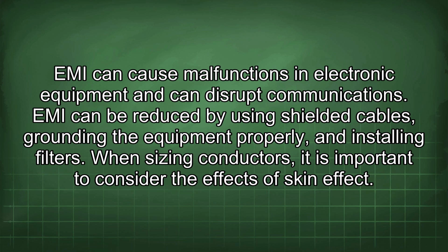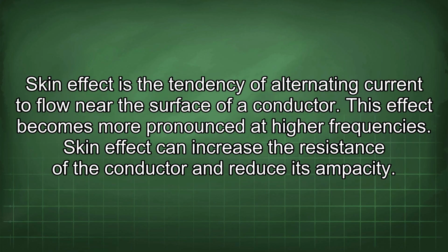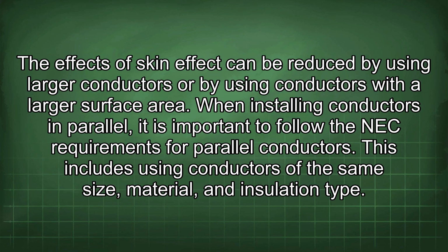When sizing conductors, it is important to consider the effects of skin effect. Skin effect is the tendency of alternating current to flow near the surface of a conductor. This effect becomes more pronounced at higher frequencies. Skin effect can increase the resistance of the conductor and reduce its ampacity. The effects of skin effect can be reduced by using larger conductors or by using conductors with a larger surface area.